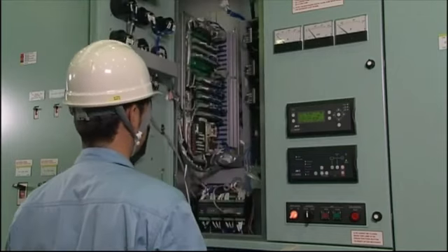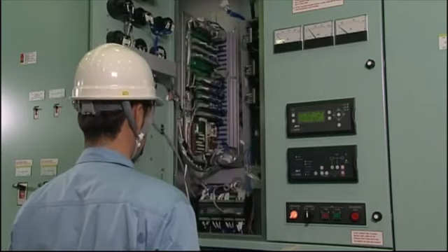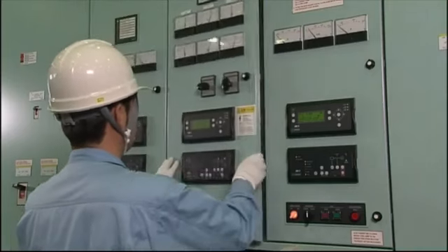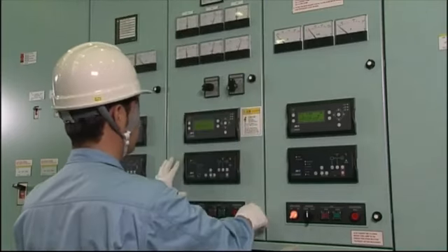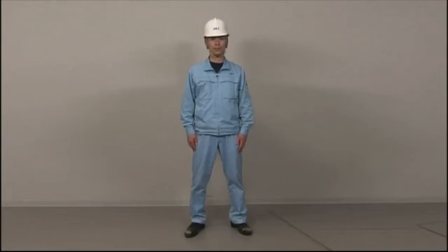When maintaining and inspecting switchboards, you should always take measures to prevent electric shock and follow the proper procedures for safe operations. Dress lightly and properly, avoiding baggy clothing and shoes with iron hobnails. Stay away from puddles and other moisture, and never touch electric circuits with wet hands.